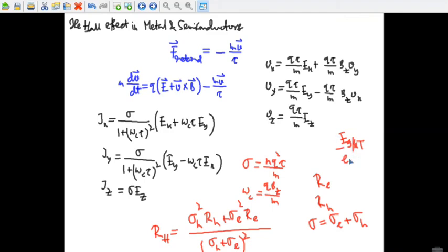The idea of simultaneous electron plus hole states has yielded a useful model of the Hall effect called the two-band model. The mathematics works through, except that the total current is the sum of contributions from the holes and the electrons.